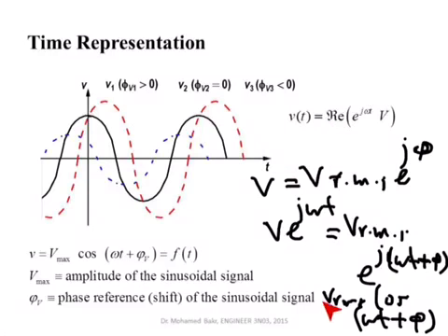Remember, here I did not multiply by square root of 2, but of course, in order to get the actual value for the time domain quantity, you have to multiply by square root of 2 if this was an RMS. In every signal that I'm going to be giving you, I will tell you whether in the time domain this is an RMS or it's a maximum. But usually when we give a phasor, it is usually an RMS value.